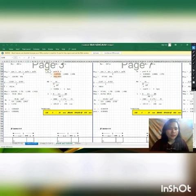So substituting the value of rho min in our As, or area, rho min times B times D, we will be having the answer of 2012.4022. So solving for our number of bars, we have the formula 4As in the numerator, all over pi d squared in the denominator. So we will arrive at the answer of 4.0996. So rounding this up, we will be having 5 bars of 25 millimeter diameter bars.